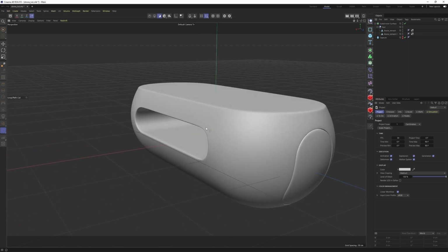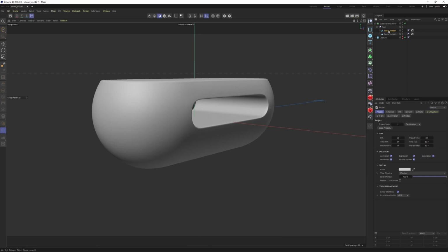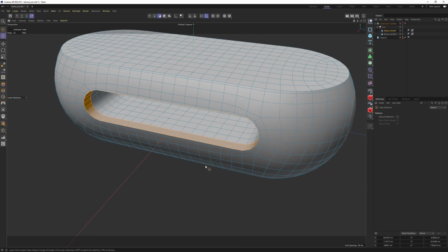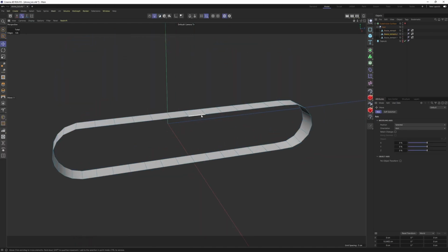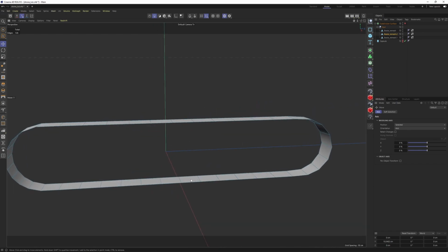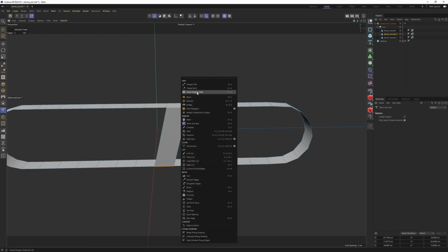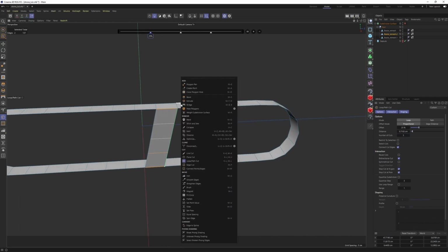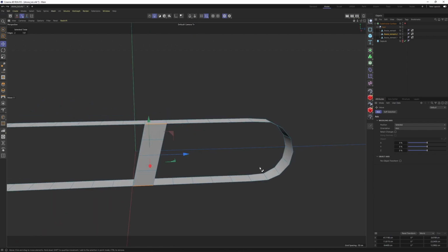Now let's work on the sides, but before doing that, let me turn off that work plane. It might be a little annoying. Okay, for this, I will make a loop selection and split these polygons, and let's solo it. As I did before, I want to close that hole. So first, let me bridge these edges, then loop cut, increase that to, let's say, 3, right click, close polygon hole tool. Now we will have a triangle, which means that we need to increase these edges.